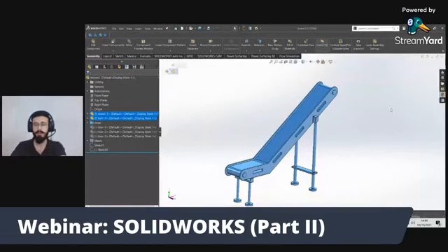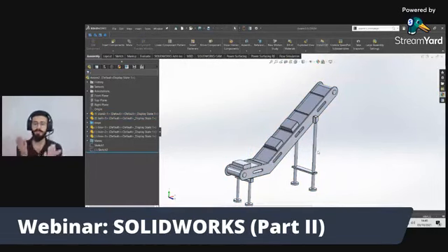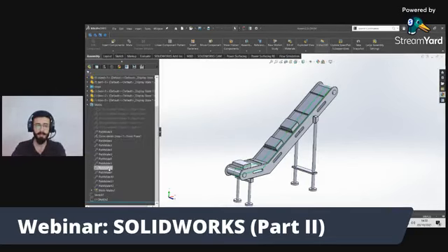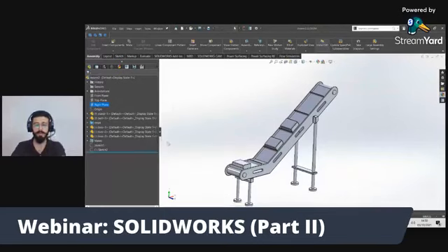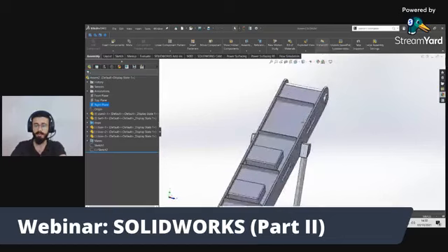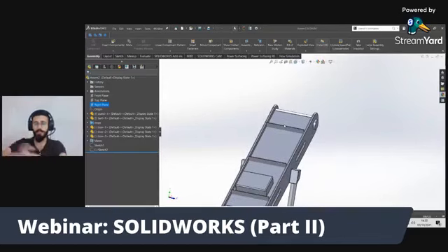This is how, if you are confused to see the mates which are being used by these two parts, like there are a lot of mates here. See, so if you got a bit confused, just select the object, go to view mates, and you can see the mates. And now the next thing is I want these plates to be movable around the